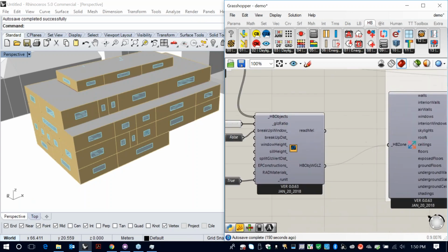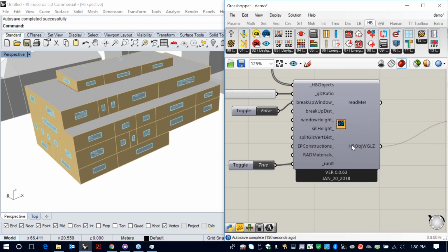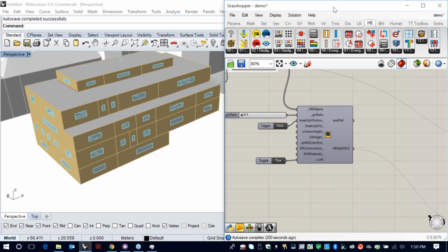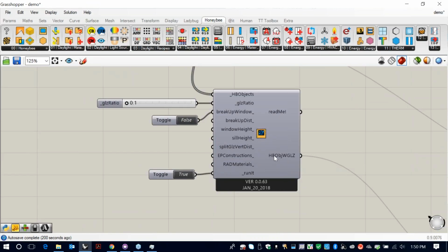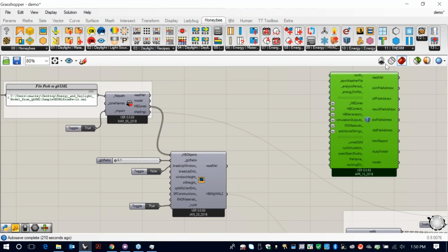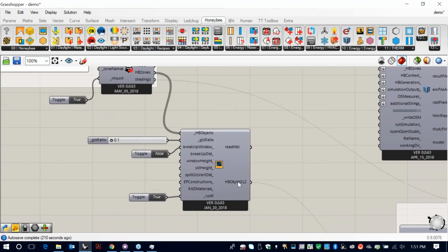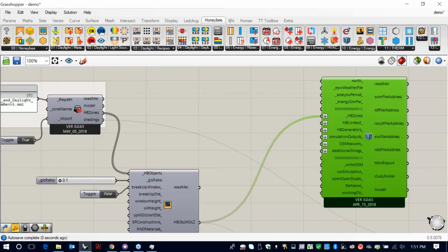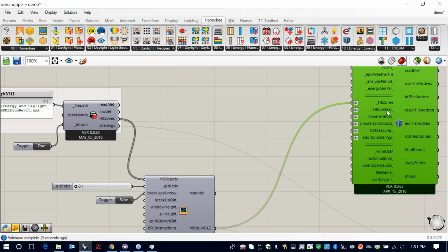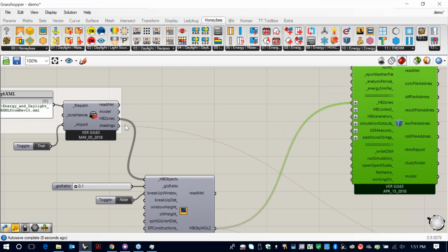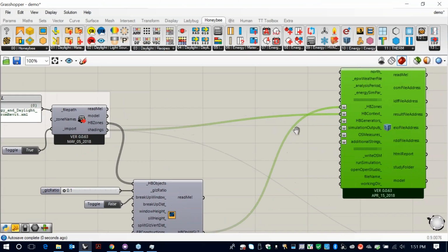All right, so now, I've been saying this whole time that these are fully simulatable zones. So I figured I might as well go ahead and prove it. We're going to take this set of edited Honeybee zones and run them through OpenStudio EnergyPlus using this component that I just yanked down here from the tab. You'll see that this OpenStudio component takes Honeybee zones as an input, so I'm going to connect up Honeybee zones right there. You can also take context shading, which, as you see, we have in this model. So I'm going to take those shadings and connect those up to Honeybee context.